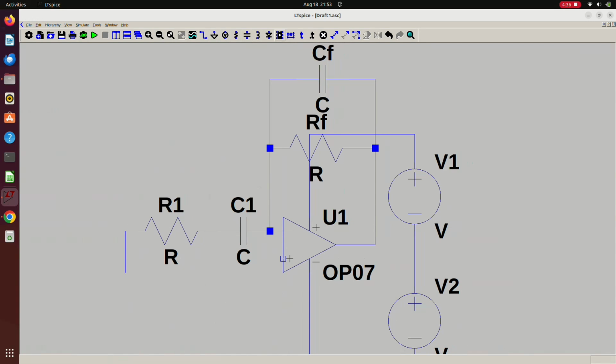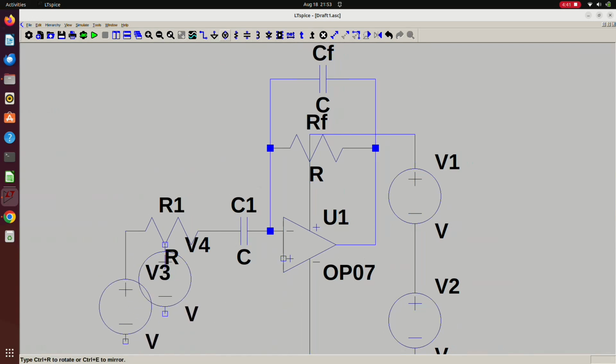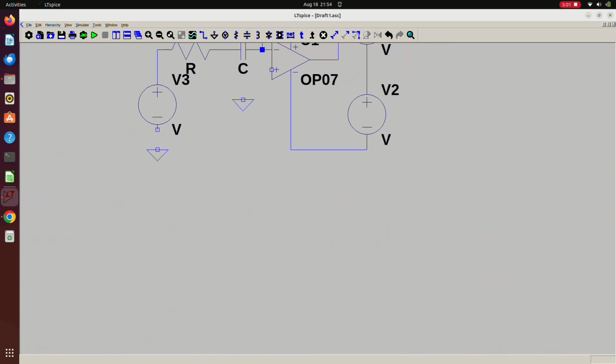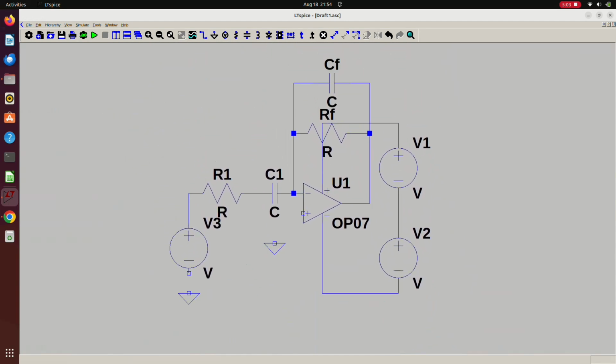So now our connection is very much complete, but I have already told you that we are giving the input at the inverting terminal. So this input is actually inverted, and because you are giving this input at the inverting terminal, it will also be differentiated. What does it mean? In the differentiator circuit, whatever input you give, if you give a ramp input, it will be differentiated. If you give a sine input, it will be differentiated. You can also give a variety of inputs like pulse input and all that.